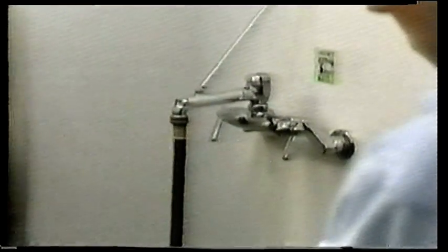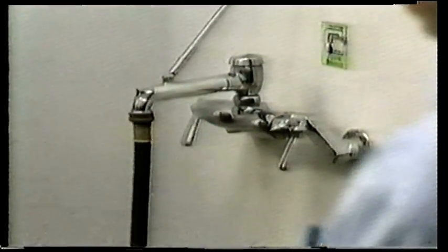The slop sink shown in the hospital survey provides excellent protection with a built-in atmospheric vacuum breaker. It is important to check every slop sink on every floor of a facility. The survey should include an examination of all laboratories. In this hospital, many different types of laboratories are present.